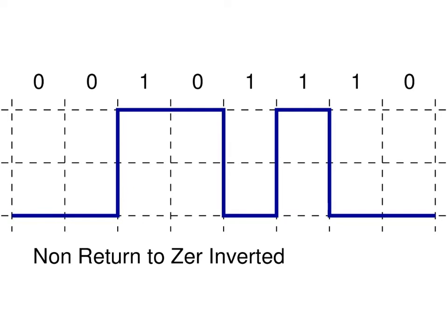You'll see on the slides it's defined, but we can also say this is one signal element, another signal element. And later we'll do some analysis and say, well, if we're sending 500 pulses per second or 500 signal elements per second, well, that's our signaling rate, the rate at which we send our signal. So in this case, 500 per second is the rate.